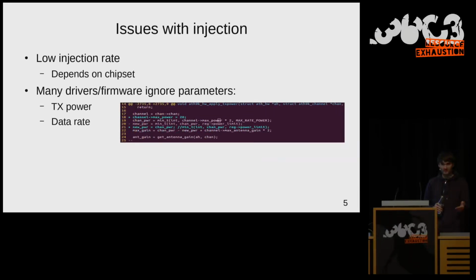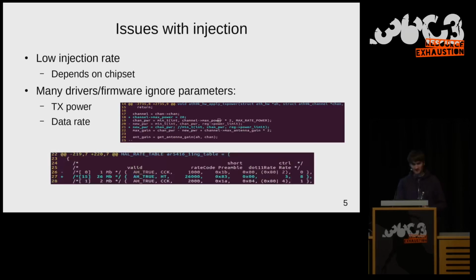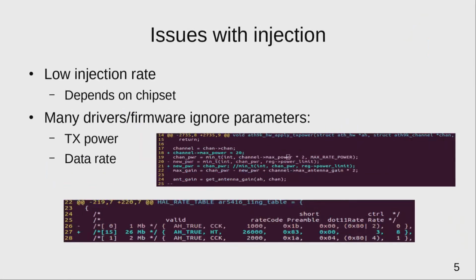So you can just download that firmware, compile it, flash it onto the Wi-Fi card, and again, to have control over the data rate, it was just a one-line change in the firmware, and I could specify exactly the transmission parameters that I needed for my project.